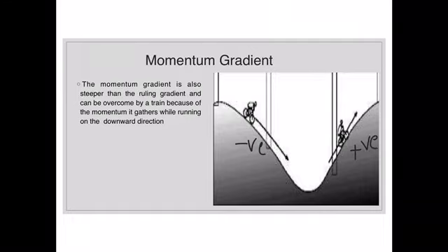So in this situation, when the train comes down the falling gradient, it acquires good speed and momentum, which gives additional kinetic energy to the train and helps it move up the upward gradient. So the momentum acquired while coming down the hill will be used to overcome the positive or upward gradient. In this section, when such gradients are provided, there should not be any obstacle, especially in the form of signals, which may bring the train to critical conditions.